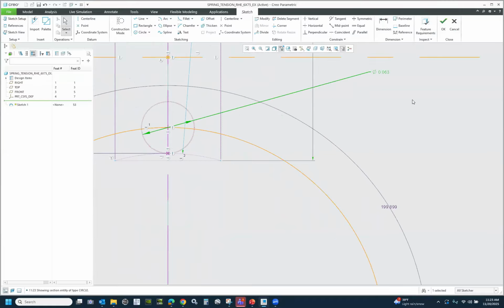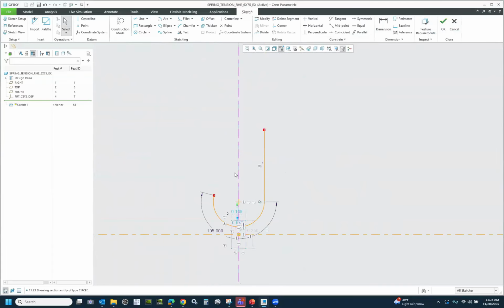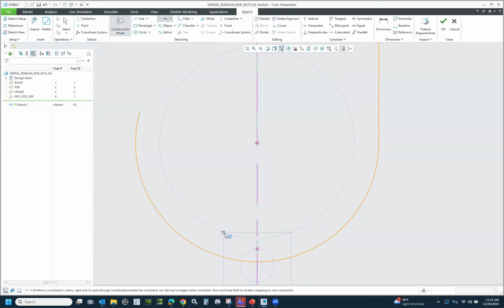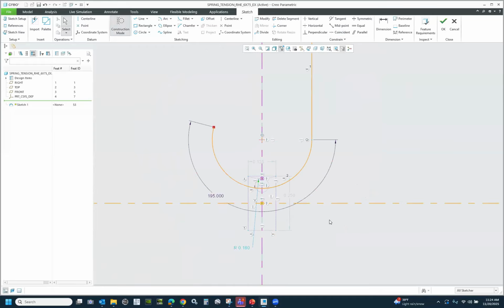And what we'll do is write a parameter that controls that. So I'm just dialing in my dimensions here, making sure I've got everything the way I want it. Everything looks good. I've got one more arc that I'm going to create right here. Then we'll make that coincident so that that point and that ride together. Everything's looking pretty good the way I want this set up.